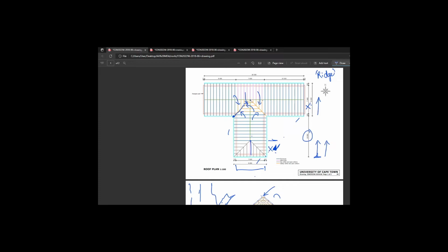Bounce, runs down into that gutter angle. There might be an outlet there, I'm not sure. I have to look quite carefully to see the outlets. It's not indicated that there's an outlet there. So it would bounce, run in this valley lining, hit the gutter, and then it would decide which way it wants to go. Does it want to go down here? Or maybe it wants to go down there? It's not picky. And that is your valley lining.